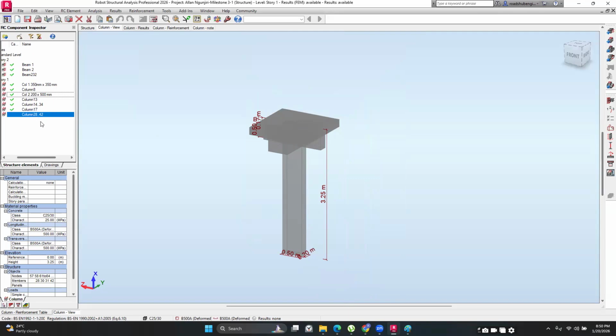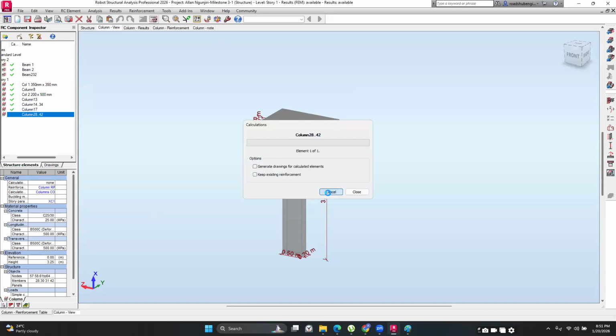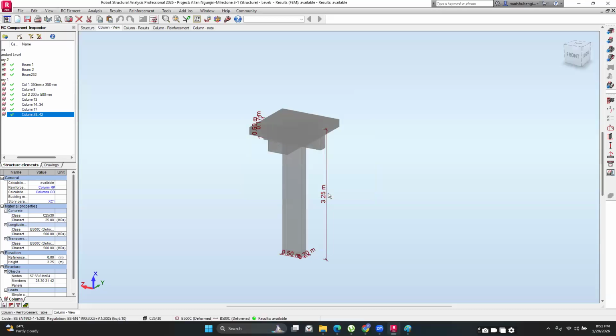But this one is even better because if they're changed together, the software will just design for the worst case scenario for you and make your work a bit easier. So select the reinforcement pattern that we created, then the calculation options that you created, and the story parameters that you created. And then after you do that, just click on calculate and get to see what happens.